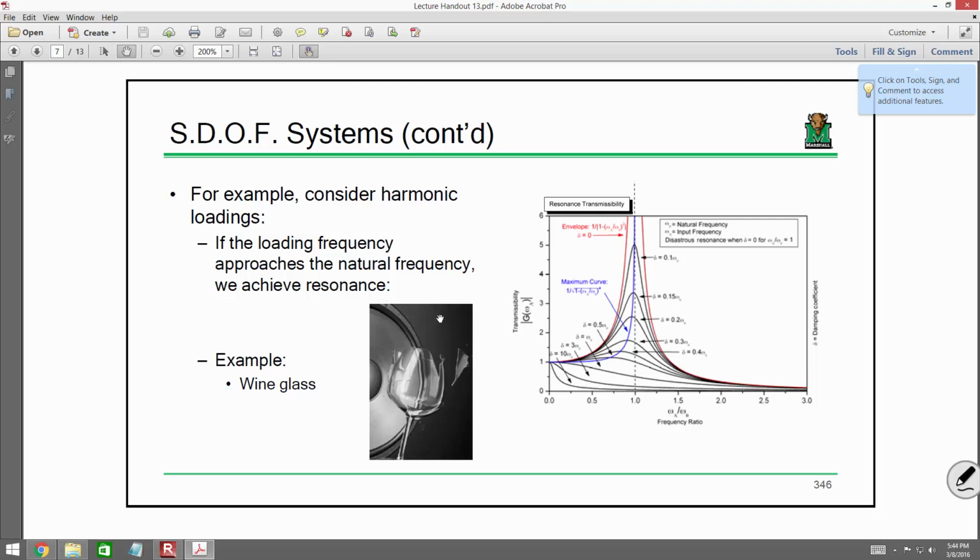That's called resonance, okay? Everybody in here, I'm almost positive, has seen that classic image of the guy or the girl singing, and there's the wine glass, and they sing, and they hit that note, and the wine glass cracks, right? Y'all have seen that, right? That is an example of resonance. That wine glass, if I take that wine glass and I click it on the table and it undergoes free vibration, it has that ding, it has that sound to it. It has a certain frequency associated with it.